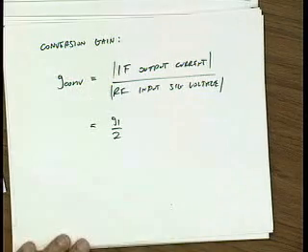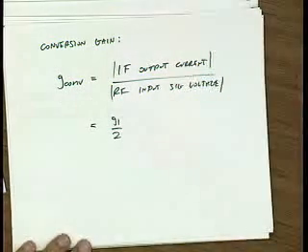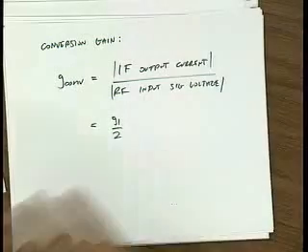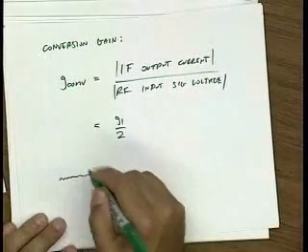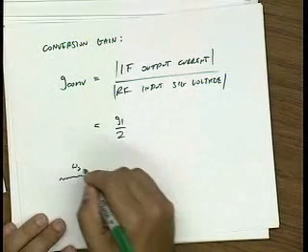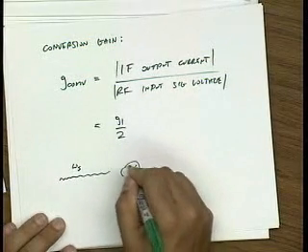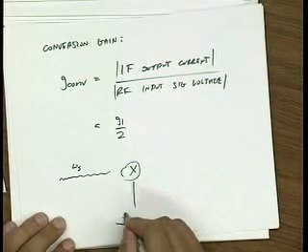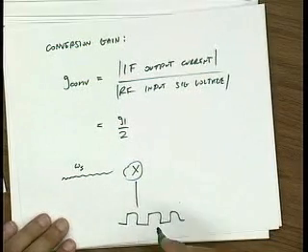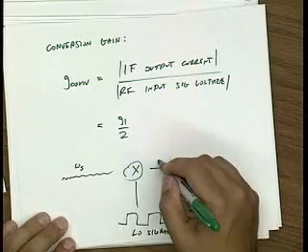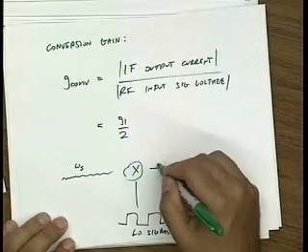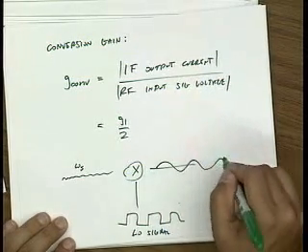So the signal comes in at frequency omega s. The output current is at frequency omega s minus omega naught. So the input is small at frequency omega s. It goes into the mixer. The mixer is getting pumped by this large LO signal. And the output could be larger, there could be gain, at some IF frequency.